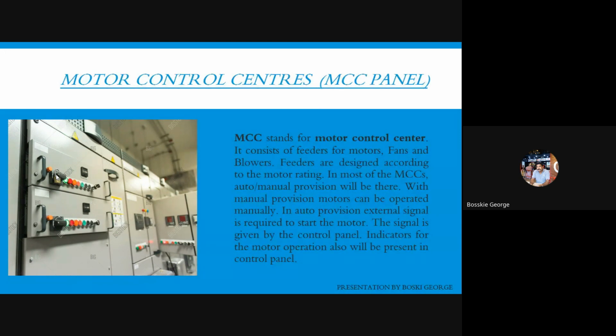If we have to select a starter for a conveyor, then the motor properties will be different. A VFD starter will be used, so we have to select VFD compatible motors. VFD compatible motors should have class F insulation and double earthing, and the shaft of the motor should be earthed separately. All these criteria apply to motors, and we select the starters for the particular motor. Then we select the VFD starters.